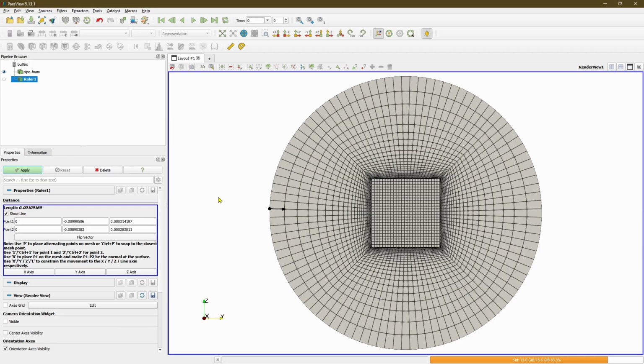Now, if I want to do that, it is of course possible. I can reduce the number of divisions in my circumferential as well as the radial direction. More likely the radial direction than the circumferential. But if I choose to do that, then that would reduce the cell resolution that I have, or rather reduce the cell count, and I'll not be able to capture the steep gradients of my parameters such as velocity, pressure, etc. near to the wall. So this is what I've chosen to do.